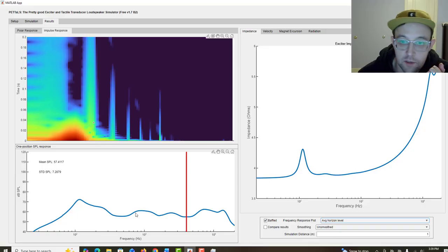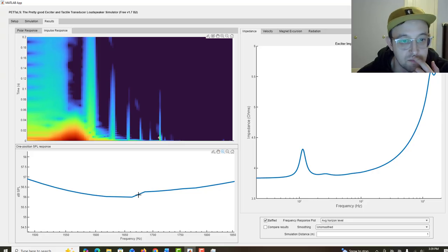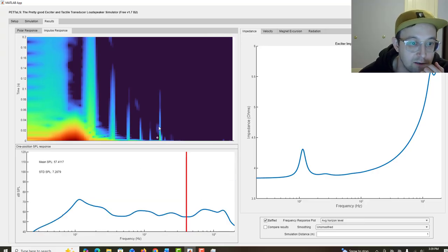Those stripes actually correspond to little discontinuities in the frequency response. If I look at this stripe here and then zoom in, there's a discontinuity in the frequency response because my frequency resolution isn't super high at that frequency. So when I convert that to a linearly spaced frequency response and then do the inverse Fourier transform, it gives me a little blip right there. So I wouldn't take that very seriously.